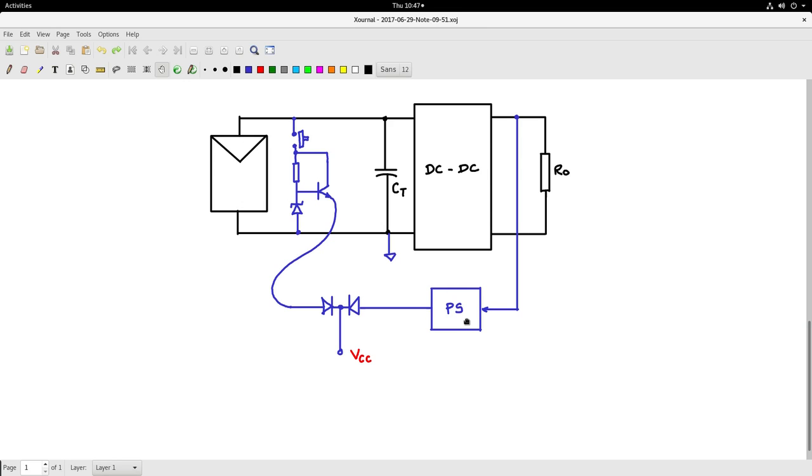Now when you take from this output side, this power supply can be any type of power supply, and most of the time this will be an isolated power supply which will have multiple windings here, and each of the windings has, as I said, specific loads that they need to supply. For example, the 3.3 volt will go to a microcontroller, the plus minus 15 volts will go to the op-amp type of circuits, and like that each power supply winding will have a function.